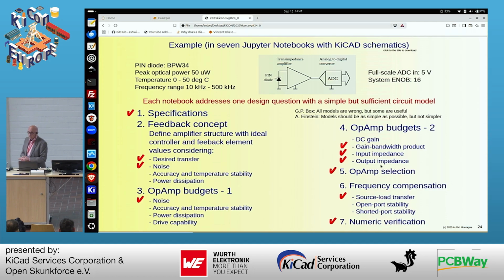But we didn't do anything about the frequency characteristic. With negative feedback, we always have the risk of making oscillators instead of amplifiers. So we need to design the frequency response. But you are not going to design the frequency response if the bandwidth is not okay. That's why we first do the bandwidth.